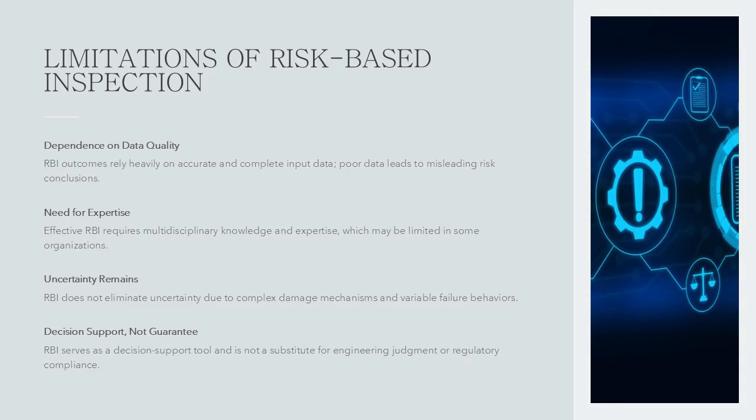managed. RBI results are highly dependent on the quality and completeness of input data, and inaccurate or missing data can lead to misleading risk conclusions. The methodology also requires significant expertise and multidisciplinary knowledge, which may not be readily available in all organizations. RBI does not eliminate uncertainty, as damage mechanisms and failure behavior can be complex and variable.